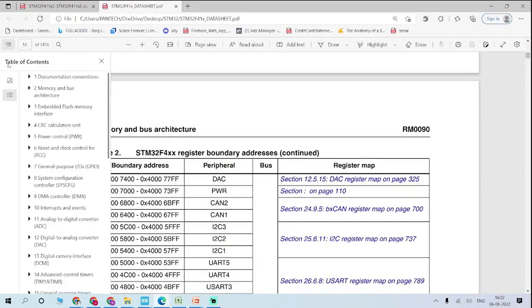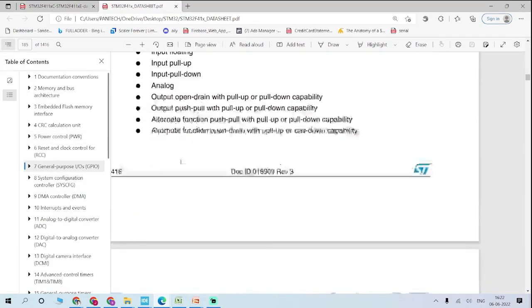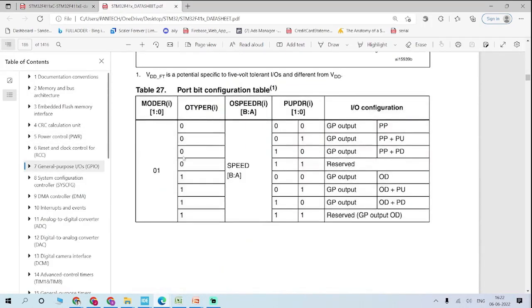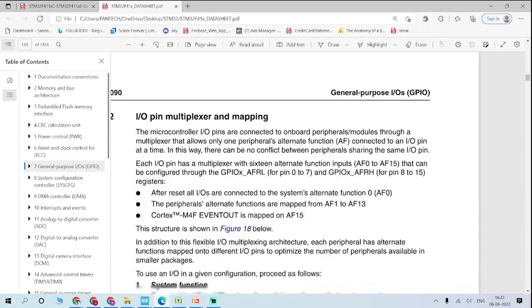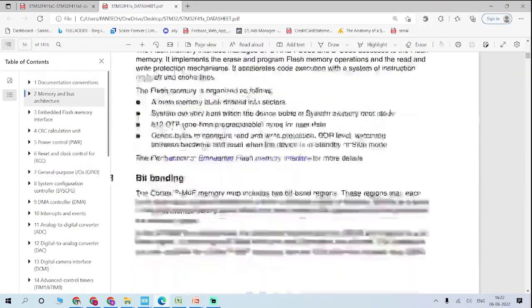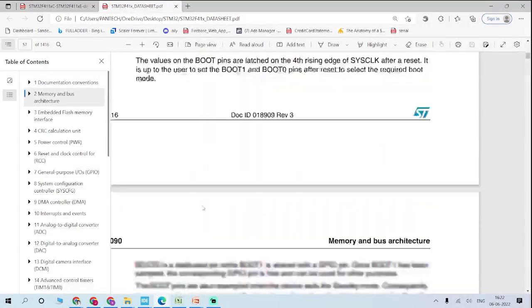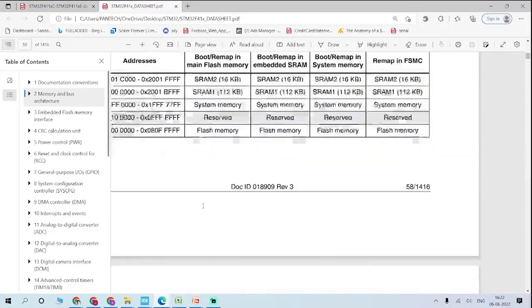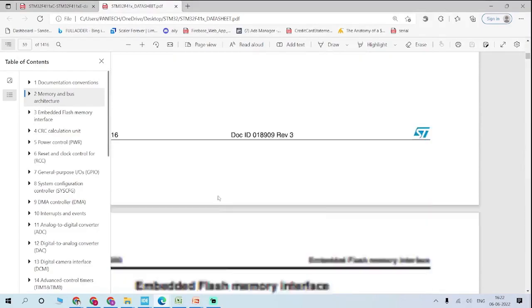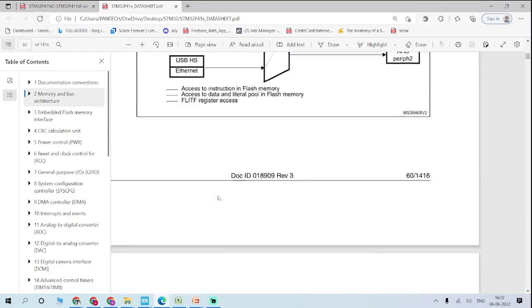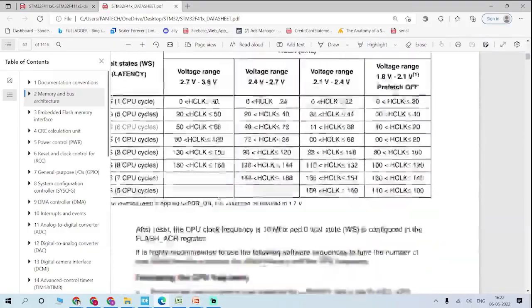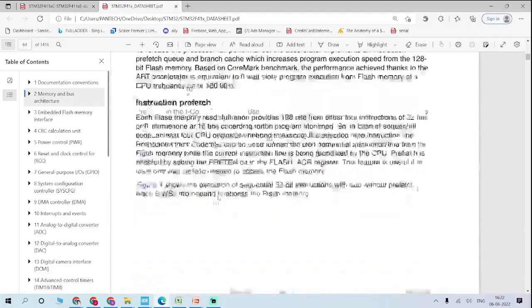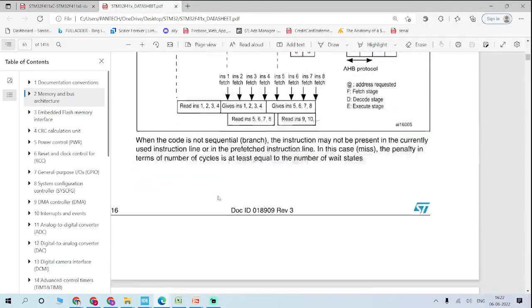Go to the GPIOs and find out the I2C pins. You can note down the page number, in order to avoid searching, so that it will be easier to refer back again.